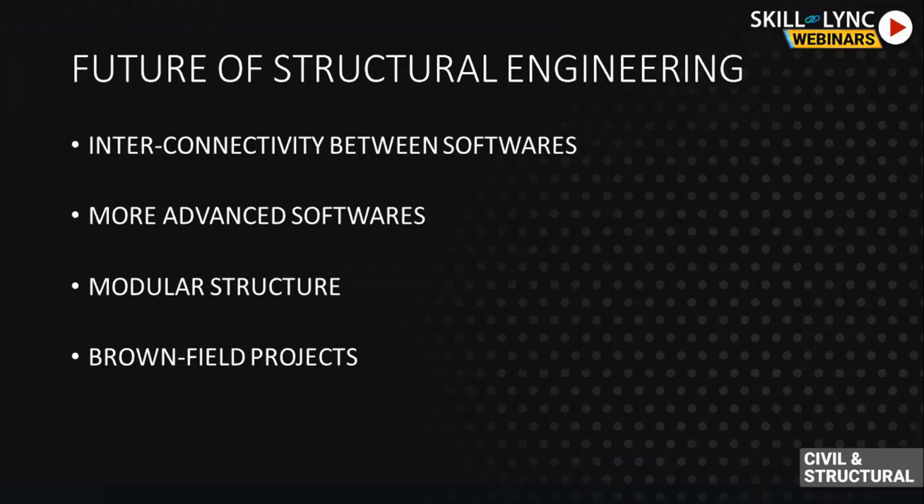So at that time, we will be dependent on these brownfield projects where we need to modify the existing structures. We need to strengthen the existing structures. We have to study the health condition of the structure: whether the structure is fatigued, if there is corrosion, if the thickness of the member has reduced, like that.